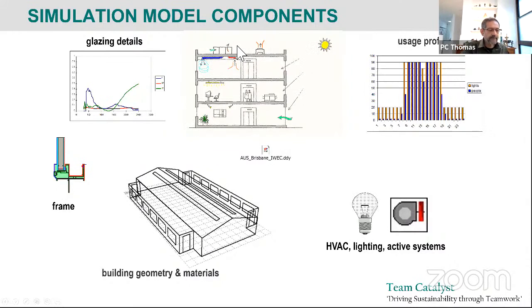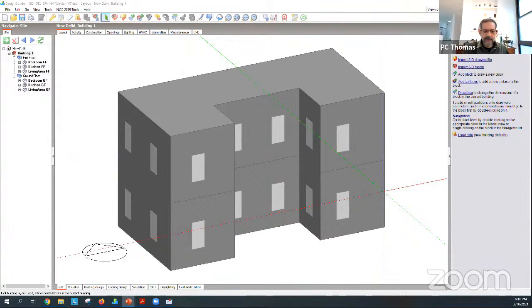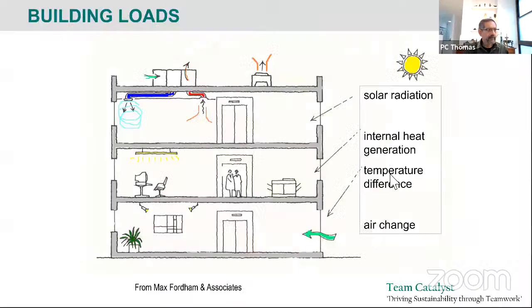So what is that? Well, the question to ask is, why do we do air conditioning or natural ventilation? The answer is that there is some heat being either gained or lost from a space. Because of that heat gain or heat loss, the space becomes uncomfortably cold or uncomfortably hot. So we have to either make it colder by doing air conditioning or make it warmer by adding heat. These things are called loads.